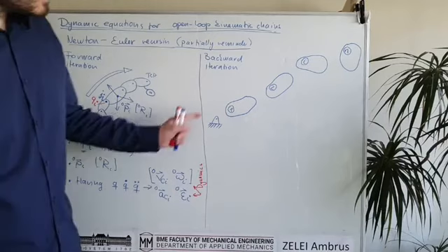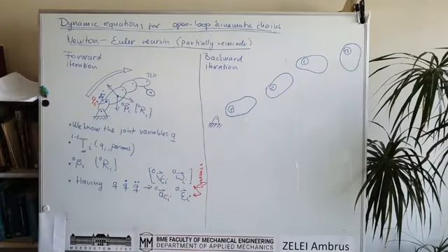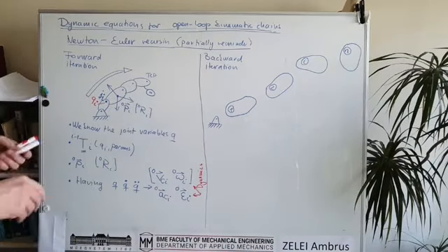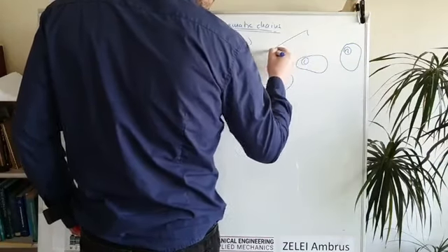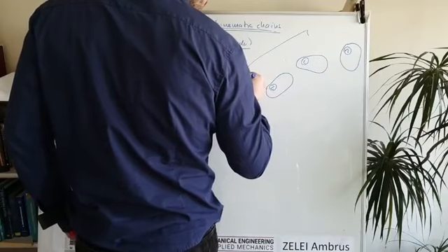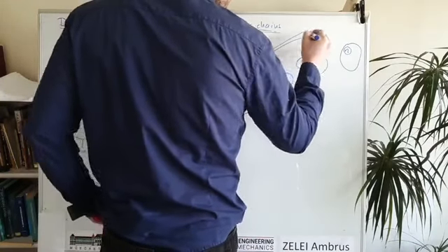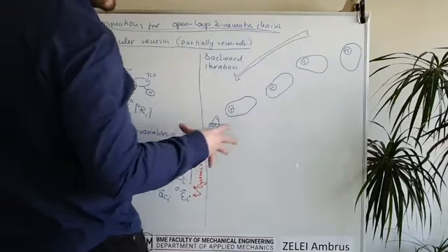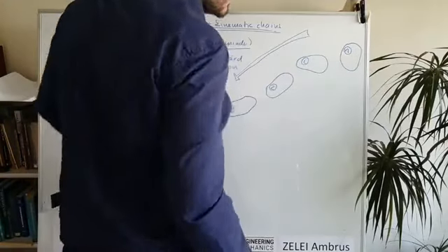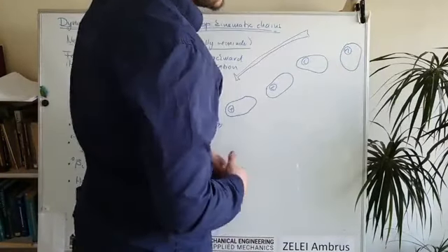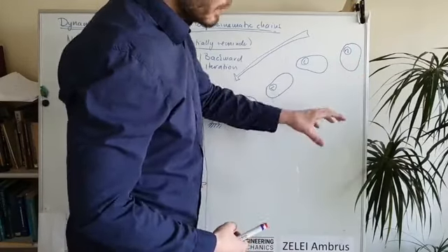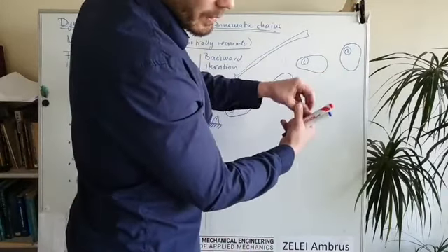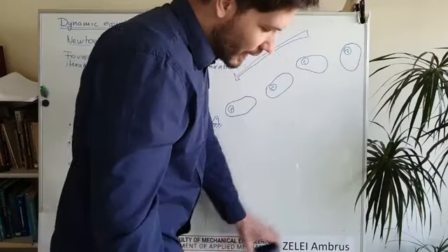In the backward iteration, we will use the free body diagrams, and we will see that it is possible to go in this direction. First we take the last rigid body and we consider all of the external forces which act on the robot, like the weight of the object which the robot grasps.